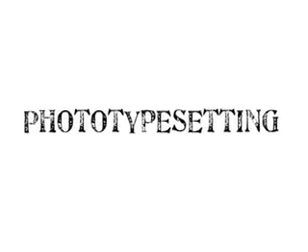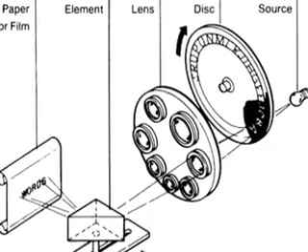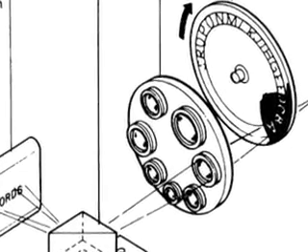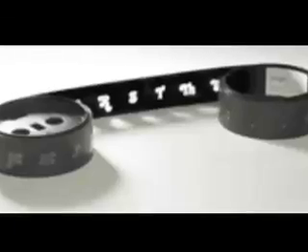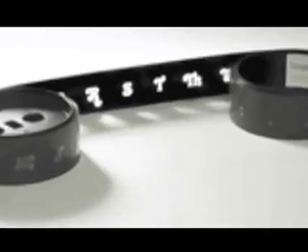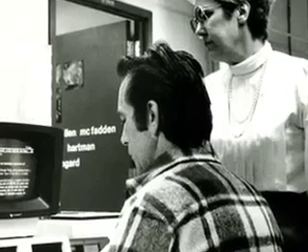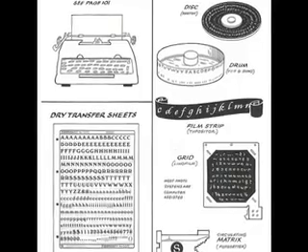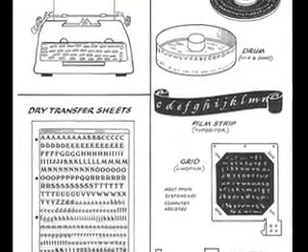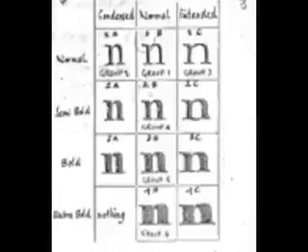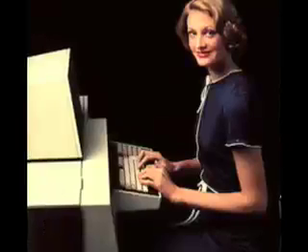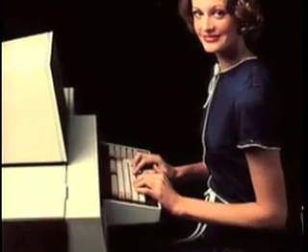Phototypesetting. Phototypesetting is a cold type process, for type is set not from molten cast metal, but by exposing film negatives of characters onto photographic paper. Although photographic typesetting was explored as early as the 1800s, its potential was not fully recognized until after World War II. As printing advanced from letterpress to offset lithography, typography underwent a similar evolution. Hand composition of metal type display and cast metal machine set text type yield to photographic typesetting.